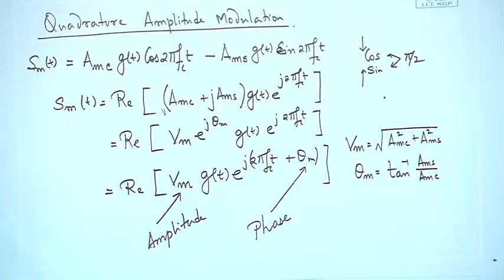In pulse amplitude modulation, you had only one signal to choose from. That means you would choose the amplitude only, and there was only a cosine, so that was the basis function. In phase shift keying, again you had only one parameter to select, that is the phase, and you chose one phase from a whole set of phases available.